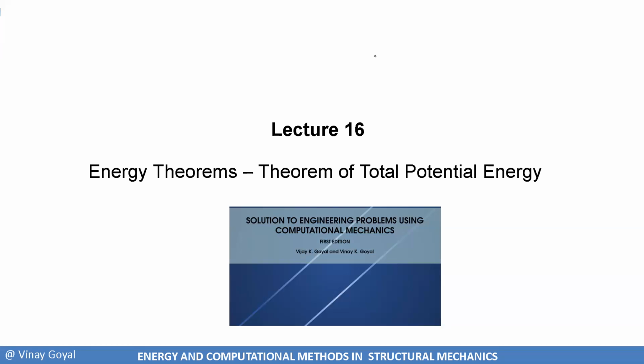And not just that, physical experiments miraculously jived very well with the mathematics. Yes, there is a way to connect these six stresses and six strains through the constitutive law. So there we had six equations as well, and three deflections, three displacements. As a consequence, we have 15 equations and 15 unknowns that somehow need to be solved over a domain.